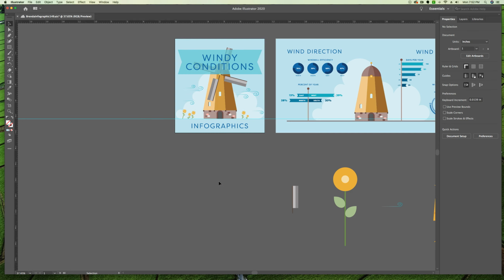At times, however, you might want to position objects more precisely relative to either another object or to an artboard. So we could use alignment options as we did in Chapter 2, but we can also use smart guides and transform options in the Properties panel to get them to move to exact coordinates on the X and Y axes.